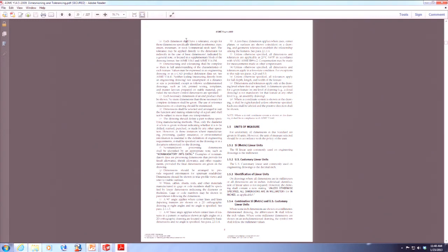In reality, I understand that forgings, castings, and weld nuts in subsequent machines are going to have a lot of slop there. But there are those who say, okay, you're putting a basic dimension up here, and 1.4 says all dimensions have tolerance. You could always add a note at the bottom that says all untoleranced basic dimensions have this.